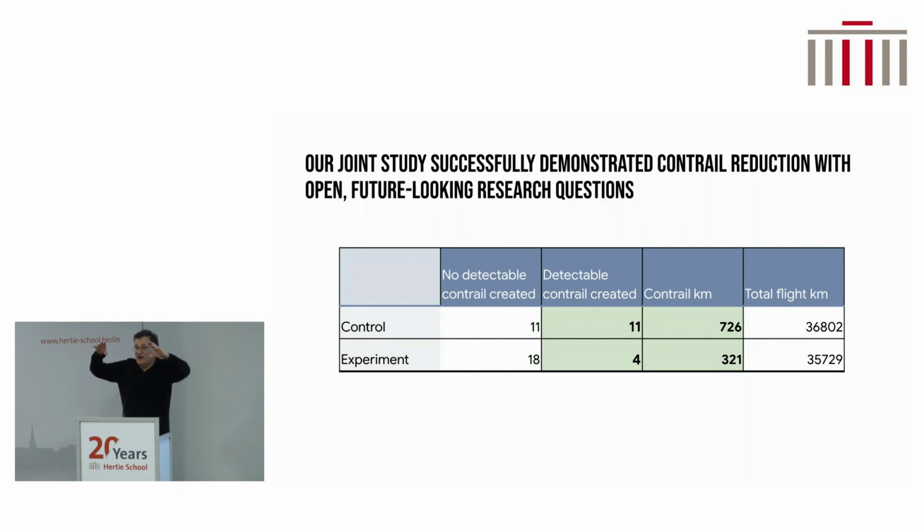And so we don't need to do the prediction an hour before. We can do it 8 or 12 hours before, still at very good accuracy, which then allows us to tell the flight planners, avoid this spot, which then allows them to determine the takeoff weight. In other words, go into the gigantic optimization. But we don't actually do the gigantic optimization because we are not experts. We just supply maps or UIs saying don't fly here, and then let them figure it out. Again, safety is an enormous consideration.